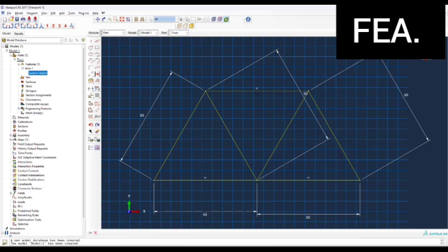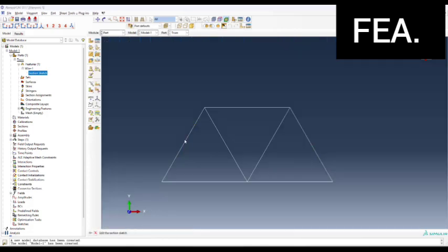Any further edits from this point will over-define your sketch. If you remember from SolidWorks, that can happen if you prescribe too many dimensions or too many constraints. It can mess with your setup because it's too much information, or if you're assigning something very obvious, it doesn't like that. So you just need to do enough to define your problem. Because if I go here and prescribe a 50, it's going to turn pink. It's just an over-defined sketch. So at this point we're done, and we have the first part of this done.